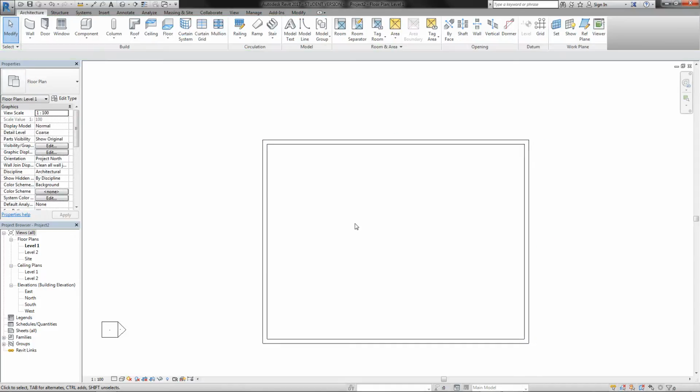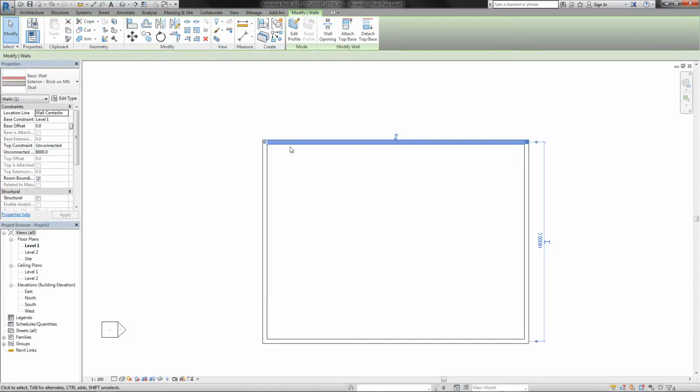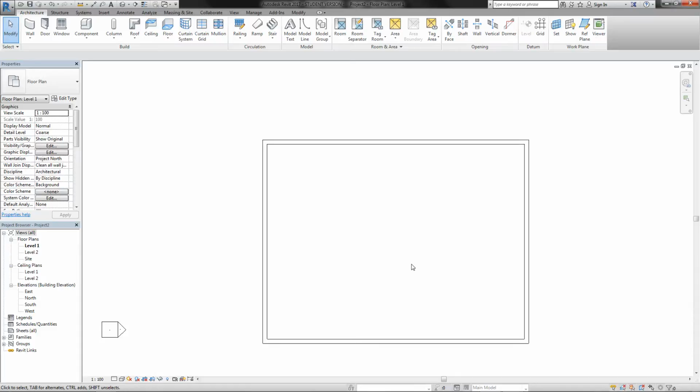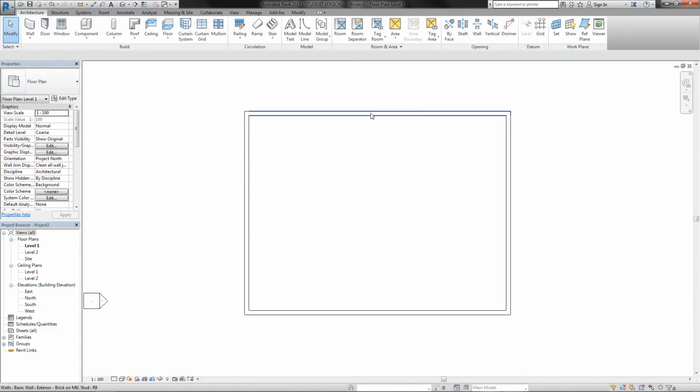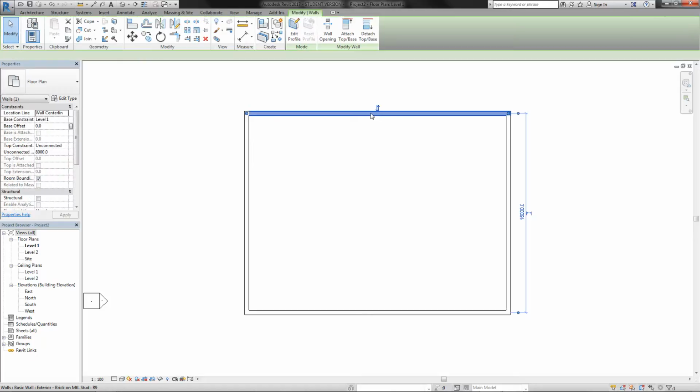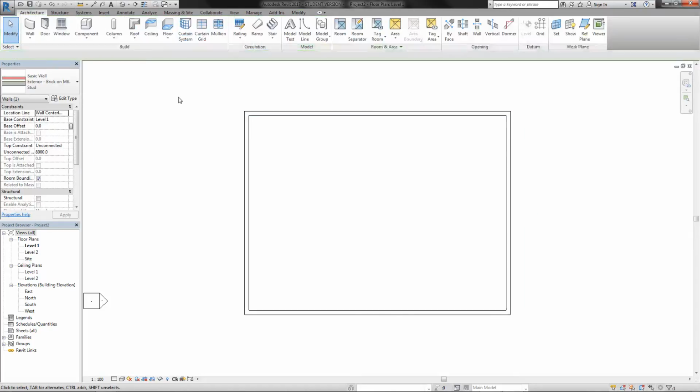So anyways, that was walls, and then you select it, you'll see different options. Also up here you have a modify tool, which we'll talk about later. But now you just know how to do a wall and then how to change its type and how to draw it. When you select this afterwards, you can also access the properties, or before drawing it, you can define what type of wall you can draw.